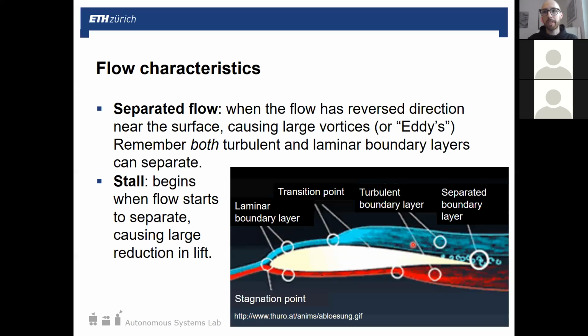Depending on the geometry of the airfoil, they actually design these to have different stall characteristics. You could have a very sharp stall. For example, very thin airfoils would often have a curve that looks really sharp. It'd drop off really fast with the separated flow. It'll go from no separation to almost full separation faster than, let's say, a wide, thick airfoil. This is not a general rule, this is just what most of the time happens. Again, airfoil geometry is quite complicated, but different designs can cause different kinds of stall behavior.